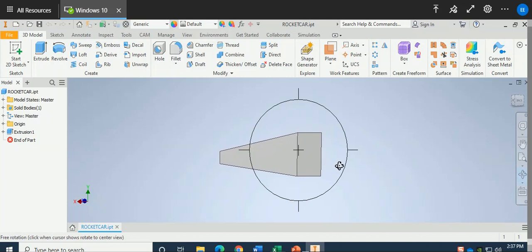That hole is for the CO2 cartridge, okay? It's critical, so we create a hole with a diameter of approximately 3/4 of an inch. It's a cylindrical hole, and the length of it is about 2.25 inches.